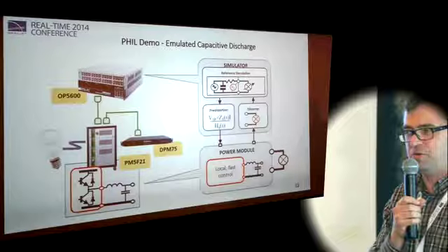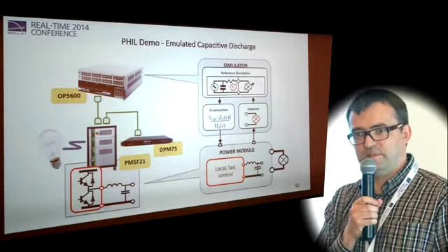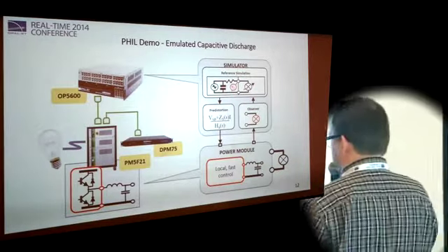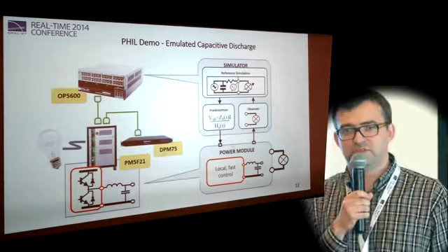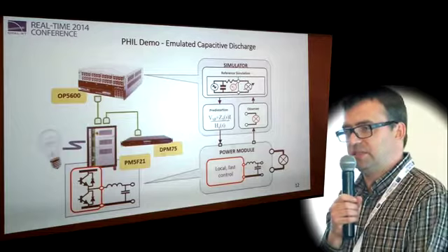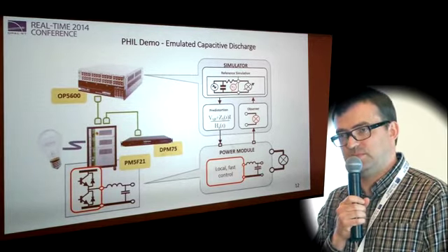No and yes. The no part is, to be honest, in this demonstration it was inserted manually, but it could be automated because the characteristic of the amplifier is known. For the moment it's inserted explicitly as one of the blocks in the MATLAB Simulink scheme. As I said, in many cases this might be a little bit overkill, as long as the dynamics of your system is slow with respect to the delay, those details don't matter.